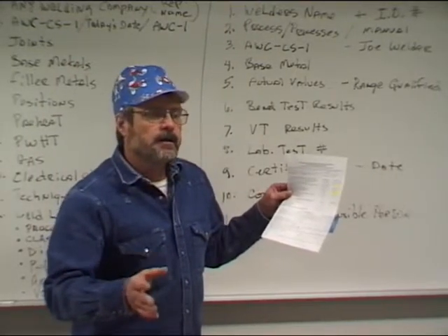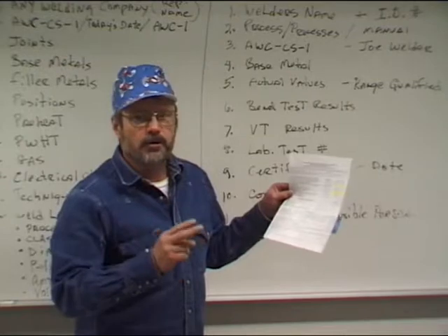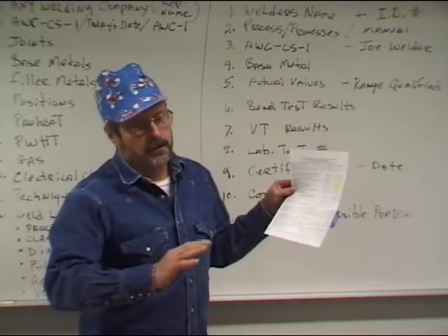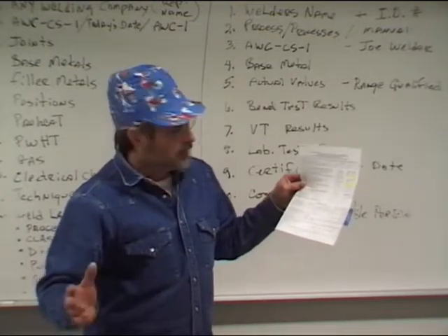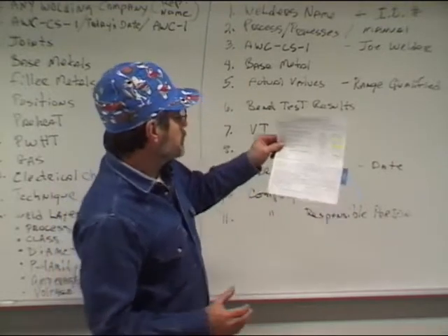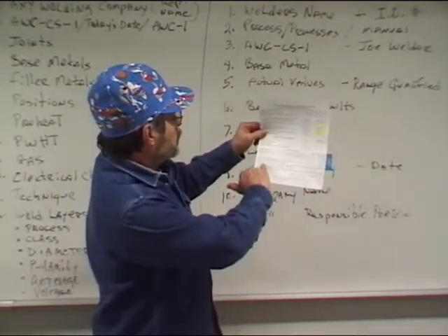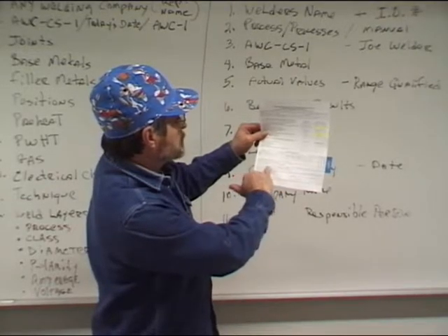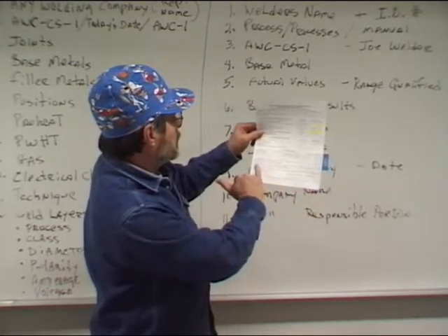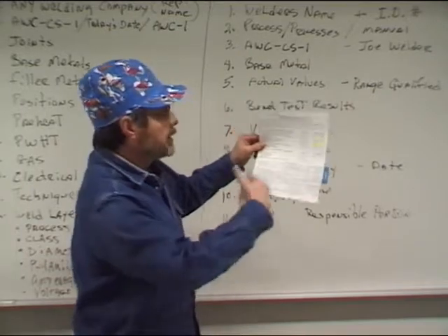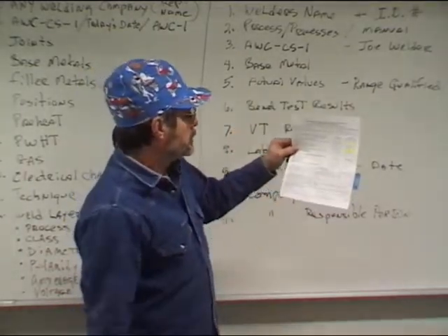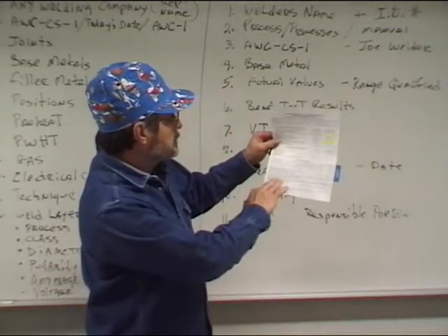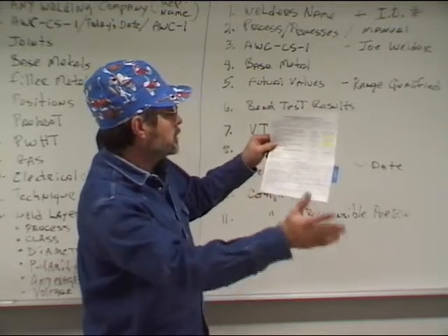Most welders nowadays are qualified just on that 2-inch super coupon by x-ray, and they'll forego the mechanical testing. But a lot of them will still require it. Fillet weld, fracture test, not applicable. Macro etch test, not applicable. Welding test conducted by, in this case we would say Western Wyoming Community College. Mechanical test conducted by Western Wyoming Community College.